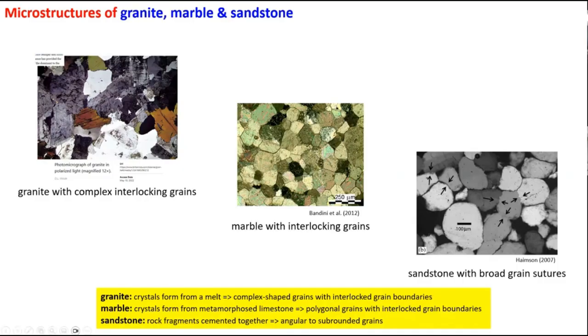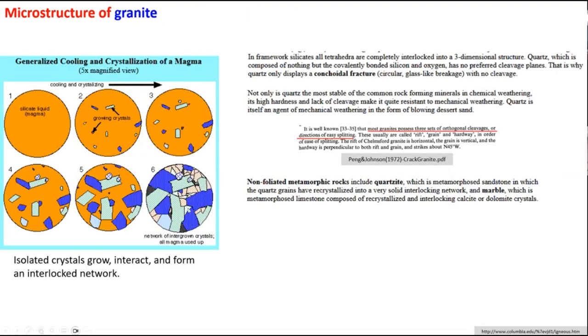The reason that the granite, when you take the core and do a UCS test on it, has that initial microcrack fabric that closes, which is what makes it stiffen, is because this thing might have formed 4 million years ago. Now it's been sitting down there, and typically it's been slowly upraised until you get to 200-300 meters underground or even to the surface. During that process, damage is occurring to this material, because when it's crystallizing there are very high compressive stresses in this system. So it's highly compressed and it locks itself together.